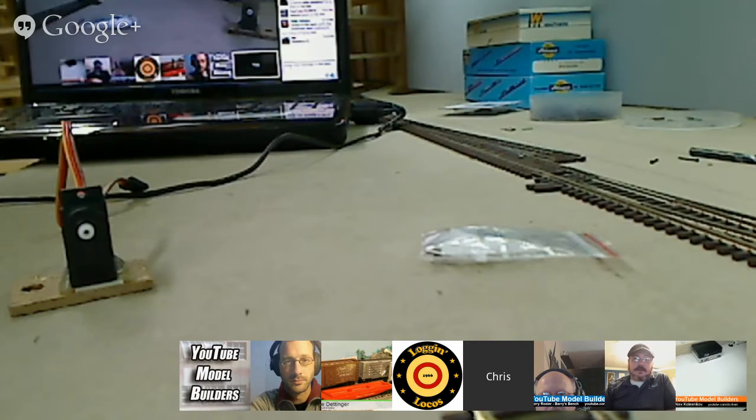Just anchor the cable at each end, and then you connect one end of the push rod to the turnout and the other end to your servo, and boom. And for staging, it's really easy. Whereas I found laying out the tortoises in my staging, they were really going to affect being able to get access to the staging tracks, just being able to reach over those. But you can lay these servos, you can drop them down almost to track level. They're visible, but it's a staging yard, so who cares?